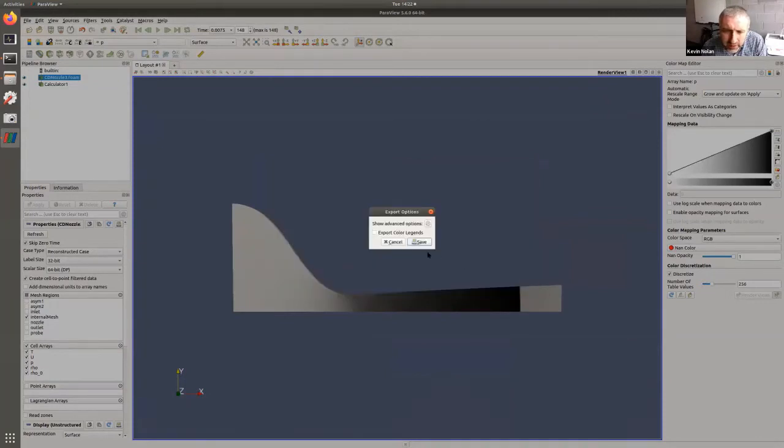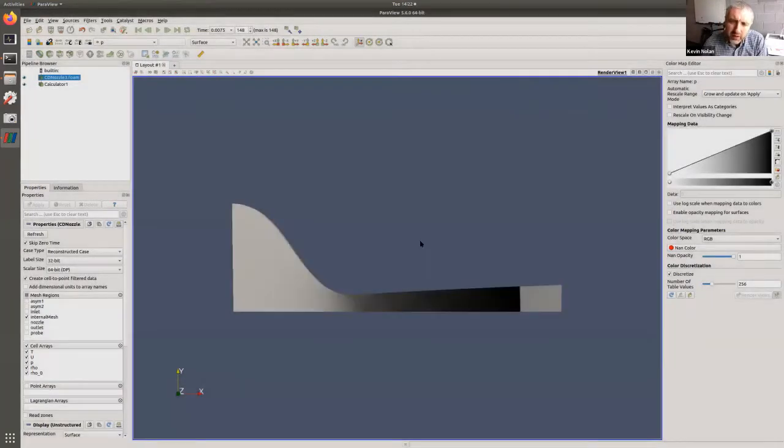Now, I am aware that ParaView is going to receive a writer for a format known as OpenVDB, so Open Volume Database. Blender fully supports the OpenVDB standard, which means eventually you'll just be able to export your entire time sequence as a volume database, and Blender will just open up and play it back. At the moment, we're just looking at single time steps.